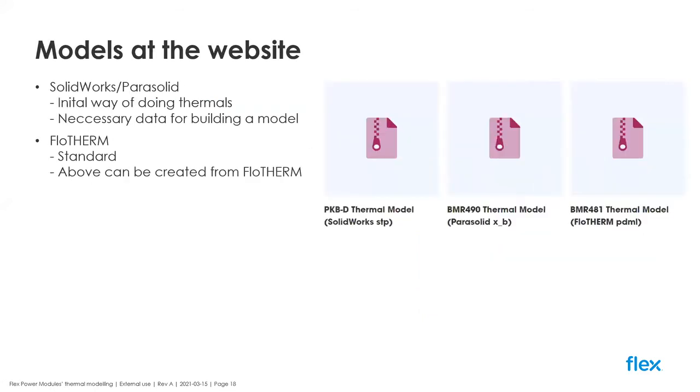So we have three different models at our website. SolidWorks and Parasolid are the older way we used to do thermal models. These are more or less the necessary data you need to build your own FloTHERM model, or also for other types of simulation tools other than FloTHERM. You can use this information to build your own model.